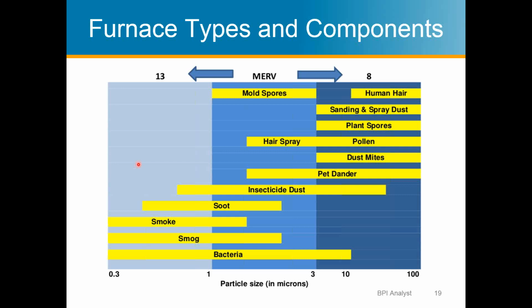You don't want to take a 40-year-old furnace and put in the very best filter you can buy, because it wasn't designed for it. MERV didn't exist back then. So you want to replace your filter with what was there already, primarily, unless you want to do some testing and make sure you're not creating too much of a pressure drop across the filter, and to make sure it's sized appropriately.